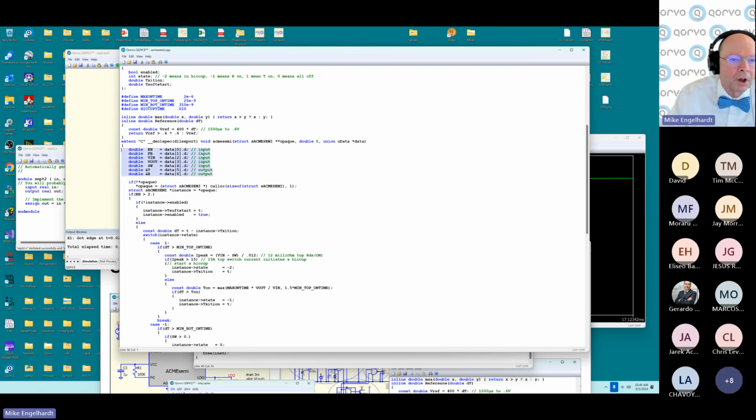Here's my function with all the pin ins and outs. Declare memory if needed. And then if it's enabled, has a threshold. If it's enabled, then look at, well, were you enabled? No, I'm enabled now, but I wasn't enabled. Then you start your soft set time and you make a note that you're enabled. So this is edge detecting the enable pin. That's what that code is doing.